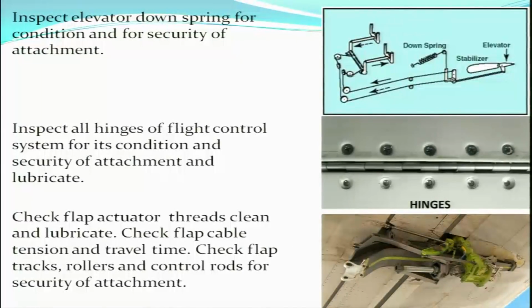Inspect elevator downspring for condition and for security of attachment. So there are the downsprings in the elevators. These downsprings are also checked for condition and security of attachment.